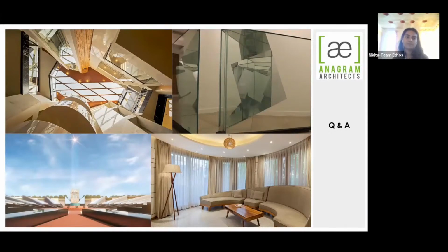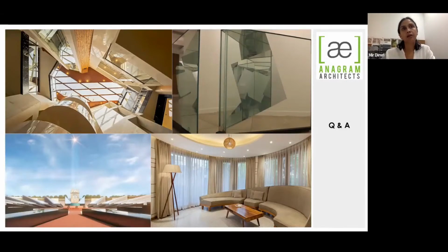So in this case, as in another house which I don't have a picture of, but we had skylights for, there are different challenges that you face that are then solved with the correct selection of glass. In another house, we had a lot of condensate under the glazing, because there was air conditioned air inside, but each time there was humid air entering, it would lead to a lot of sweating on the glazing. So we had to change the kind of glazing that we had used, and we had to give a bigger gap between the DGU unit.